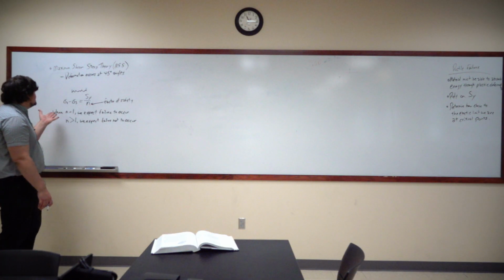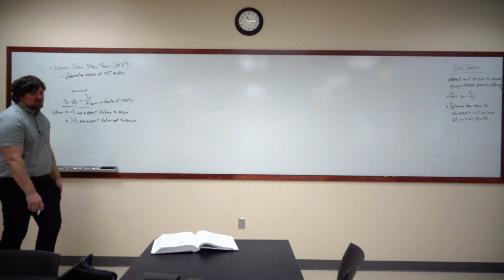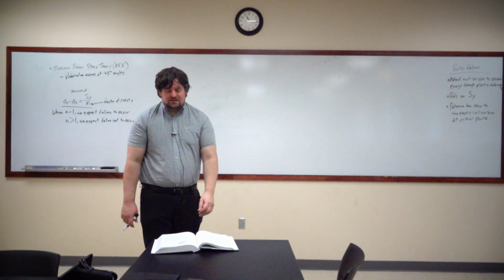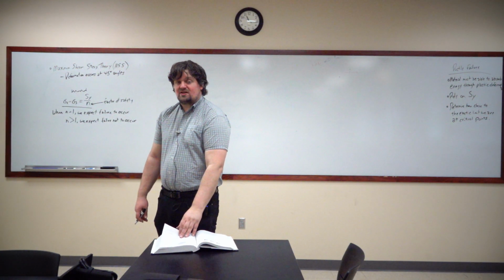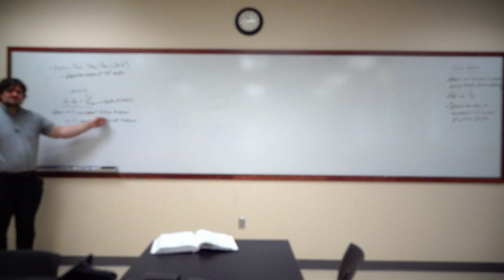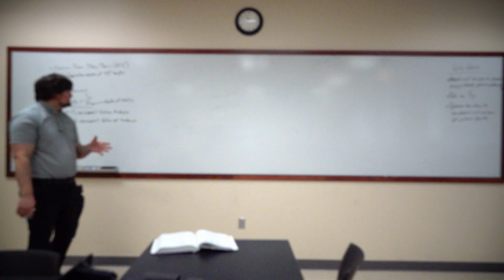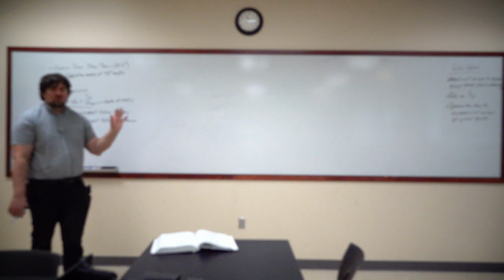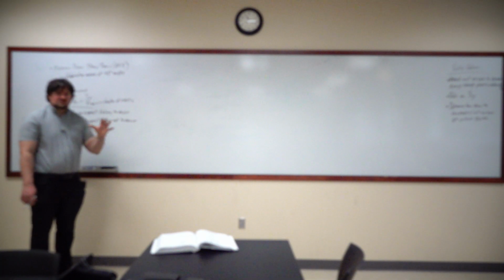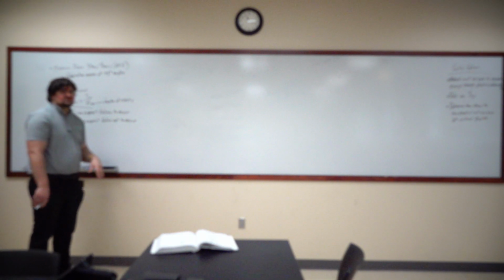So that is this equation. Now this is the easiest equation to use because you only have one. This is it. And there's no real variability. The problem is that maximum shear stress theory is very conservative. What we were finding is that even though at the n equals 1 value we're supposed to be expecting failure to occur, we were actually seeing that closer to about 80 to 90% of samples were still working at n equals 1, and even values of n slightly less than 1. We were seeing a lot of these samples were still functional, we're actually still good. So it says, well, we're being a little conservative in how we're calculating our n value using maximum shear stress.